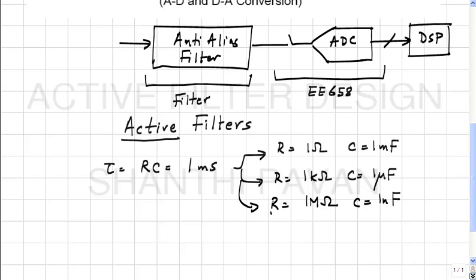It turns out that resistors not only resist but they also add noise. Those of you who have not done noise, don't worry about it, but it turns out that the larger you make the resistor, the more noisy the filter gets. In other words, the filter whose job is to take a signal, separate it in principle into two components, reject one component, send out the other, is now also adding its own noise to the whole process. So it's therefore corrupting the wanted signal. As R becomes larger, the noise due to the resistor becomes larger and is therefore causing more corruption of the desired signal after filtering.